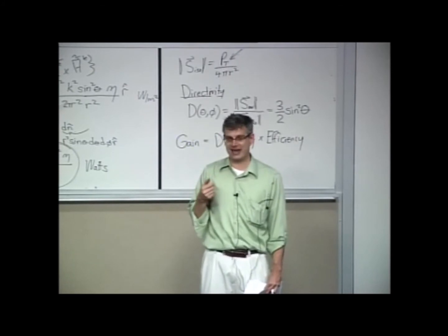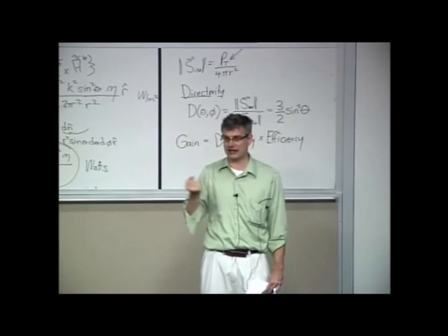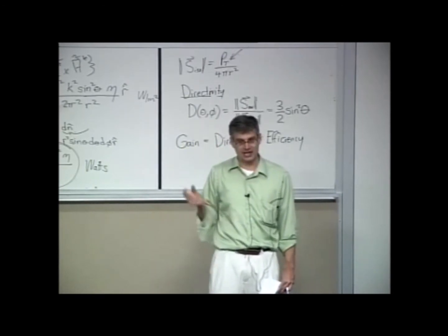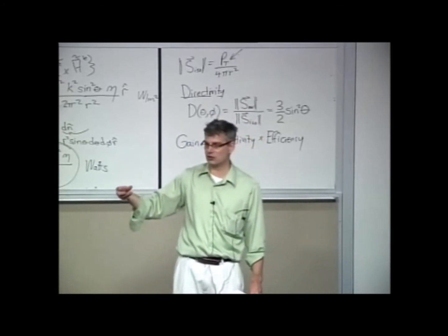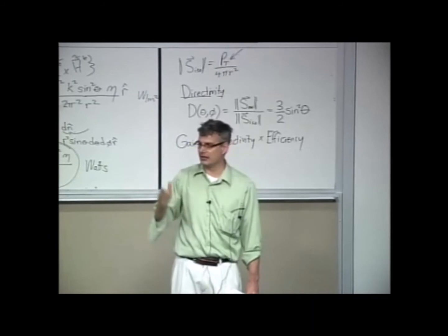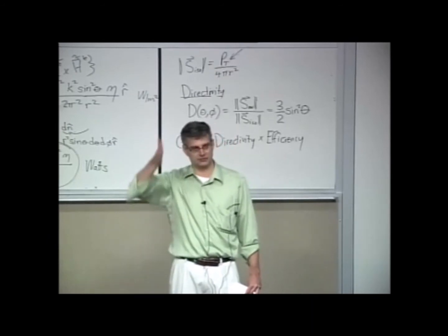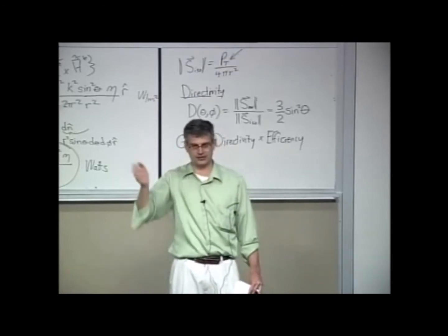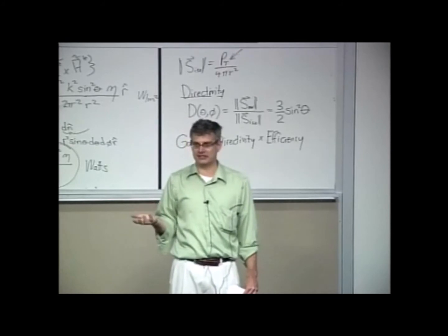So if an antenna has a certain impedance, well, so does the line that feeds it. You have a transmission line leading up to that antenna. That transmission line also has a natural impedance. If it's not the same as the antenna, then a portion of that signal will reflect back to establish the proper boundary conditions to allow voltage and current to be continuous across the boundary from the transmission line to the antenna.